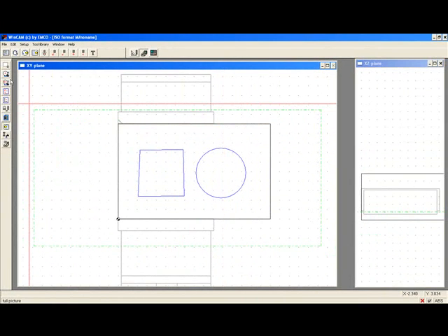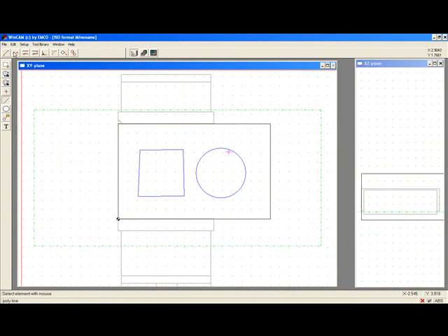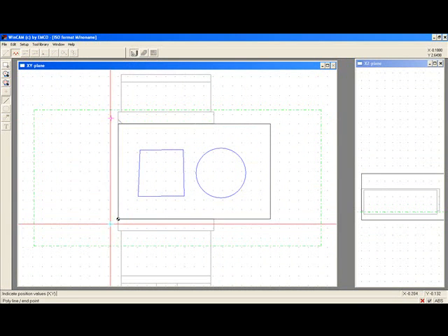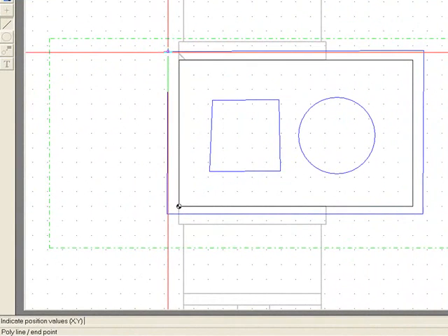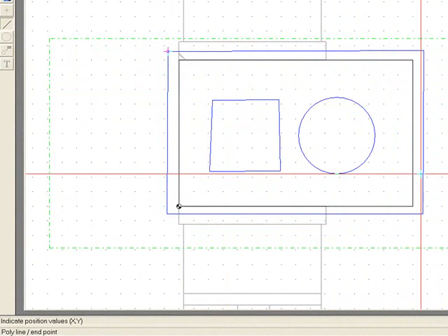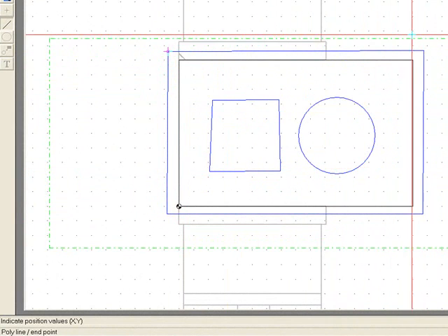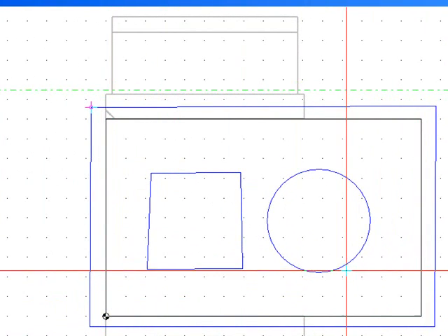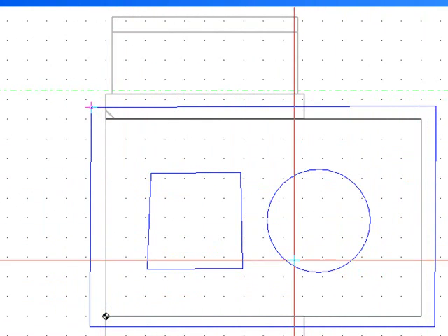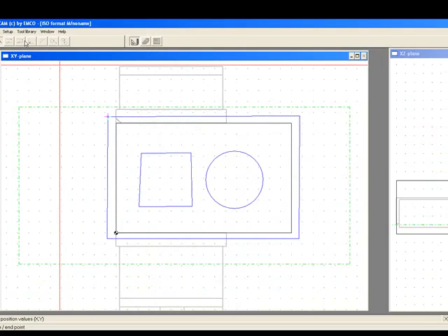And what I'm going to do is first go back to my CAD drawing, which is this function right here. We're going to select polyline, and I'm going to draw outside just by a little bit a polyline. I'm just going to keep it as close to a good right angle rectangle as I can. Right click, search point so I make sure it's connected. And then we've got that nice rectangle. Okay, so that forms what we call our outer contour. And what that's going to do is make this machine mill out all of the material around our two geometries.